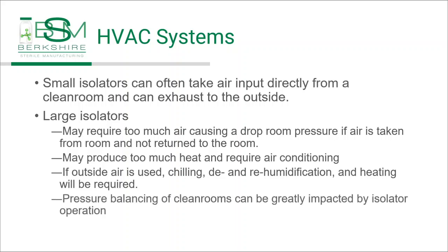And pressure balancing of clean rooms can greatly be impacted by isolator operations. We've had, in installing isolators, situations where a small isolator actually dropped the pressure in the room because it was taking too much air, so we had to go and rebalance the clean room. We also have a large isolator that takes 100% outside air and exhausts all of that. But when the mouse holes are open, air is coming out of the mouse holes into the clean room, and we actually see the pressure increase in that room when the isolator is in operation.